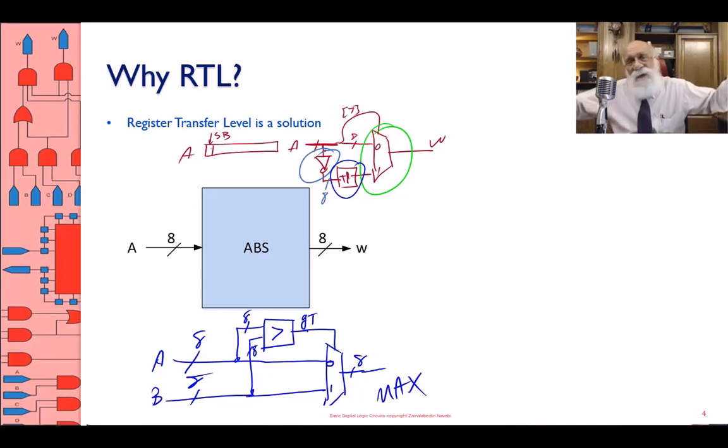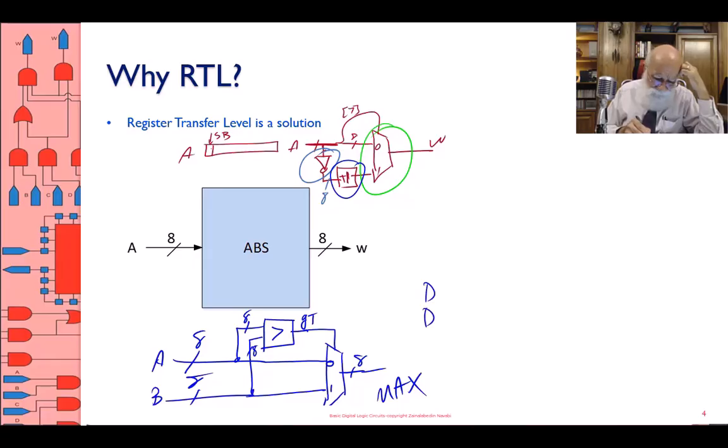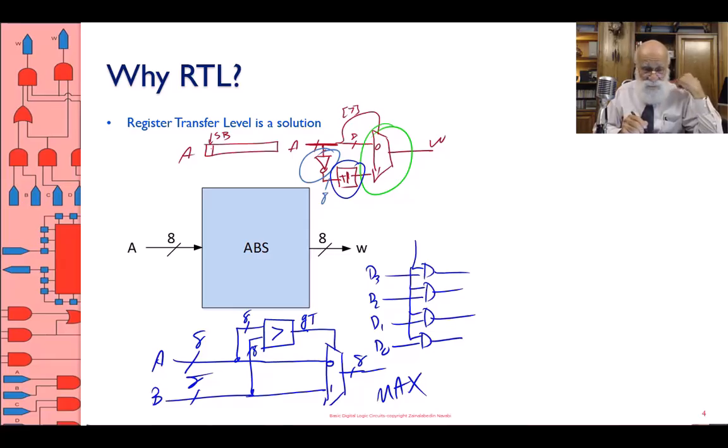An array of gates, yeah, array of gates is easy because in one case maybe I need to select either my, let's say data 3, data 2, data 1, data 0, or I want to have 0 selected instead. So if I put a 1 here, D goes to the output. If I have a 0 here, 0 goes to the output. So an array of gates comes handy a lot of times.